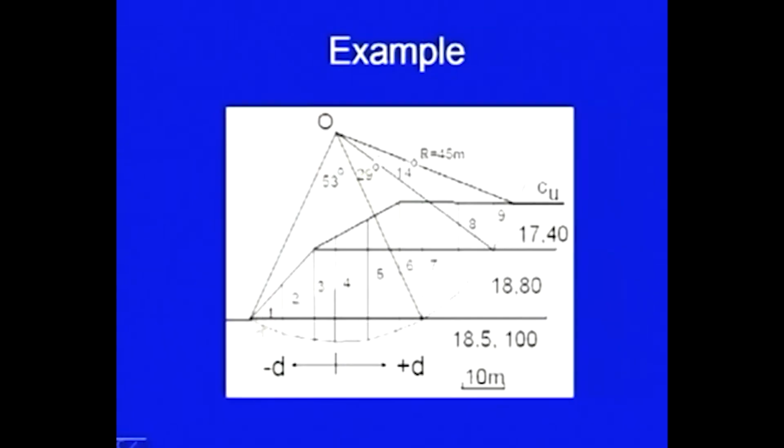So, I have kept here these slice number 1 and 2, they are having same width, third is not having the same width. And also second point, one more important point is there, because in this particular example the profile is changing. Here the angle is almost 45 and here it is flatter angle. So, we should also keep one slice ending at this particular place. So, with these points the calculations will become simple.